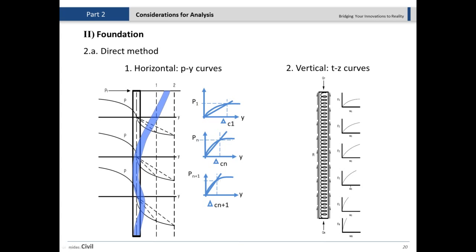They're asking about considering the damping in the soil springs. You can consider the damping in the soil springs, yes. The damping will be considered as a linear damping. So yes, we can consider that one. But what the value is depends again on the soil. I believe something like 5% or less would be considered here.